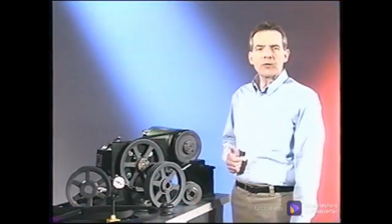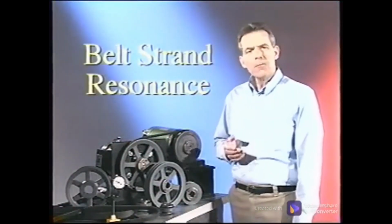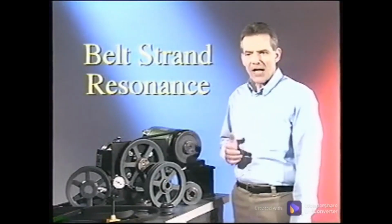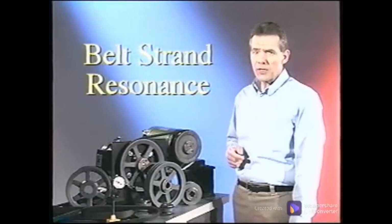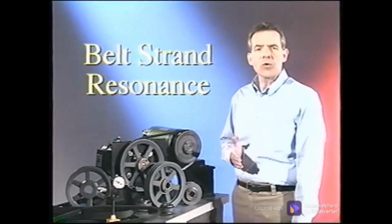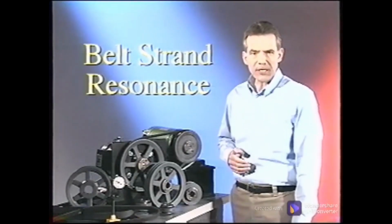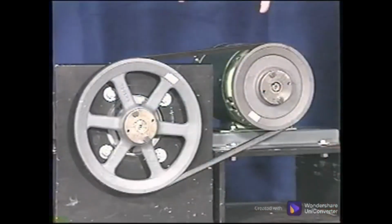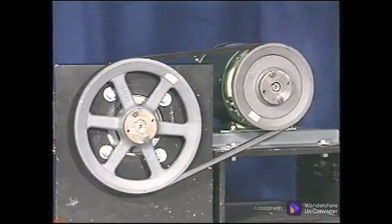The most often ignored belt-related vibration source is belt strand resonance. Belts, like any other component, have one or more resonant frequencies, and that resonance can literally destroy a machine when it coincides with another resonance or a fundamental frequency, such as shaft turning speed. The belt strand is the free or non-contact length of belt between the sheaves.